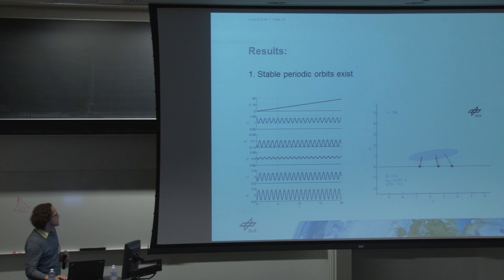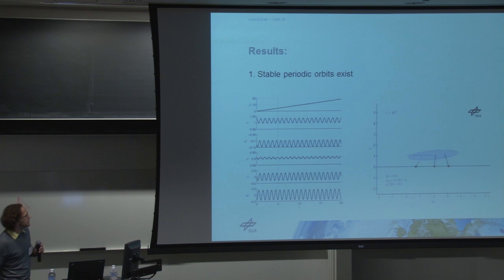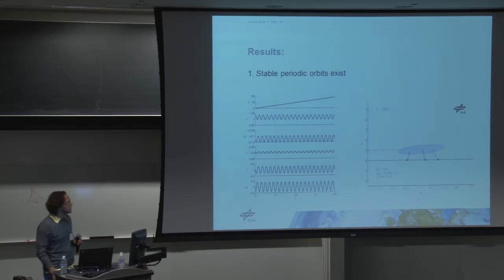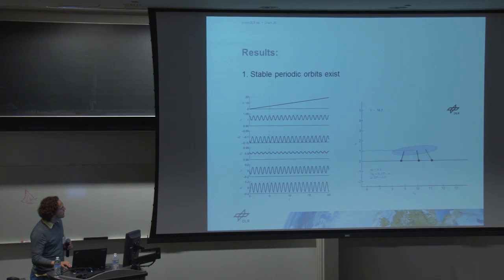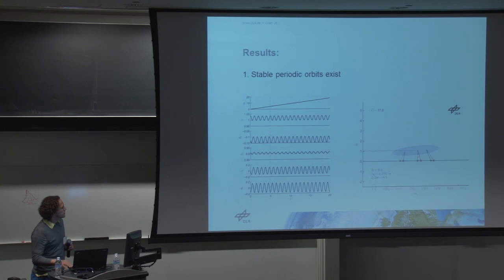So what do we see for this model? If we pick the right set of parameters, we get some very nice periodic gaits that are stable and robust and can handle step disturbances up to maybe 30% of the hip height, and also force disturbances, short force impulses, which are 10 times the weight, and no matter which direction.